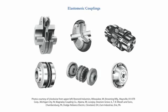Here is another design family of couplings. These elastomeric type couplings use some sort of flexible yet resilient material such as rubber or plastic to accommodate a slight misalignment condition. Examples here show rubber tire type couplings, rubber insert couplings, and rubber gear type couplings. These couplings do not require any lubrication like mechanically flexible couplings do. But if you remember, the first 4 couplings you looked at in the misalignment study a few slides back were all elastomeric couplings, and the elastomer was getting hot.